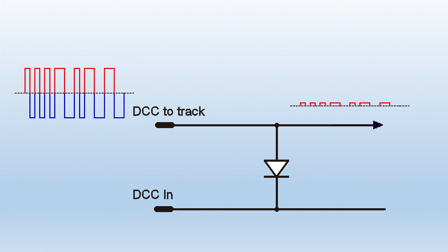The positive going half cycles are going to bring the diode into conduction, current will flow through it, and the negative half cycles will be blocked as you would expect. And on the right hand side you'll see a much diminished voltage because all we're looking at here is the 0.7 volts developed across the diode itself. The great majority of the incoming voltage is across the motor.